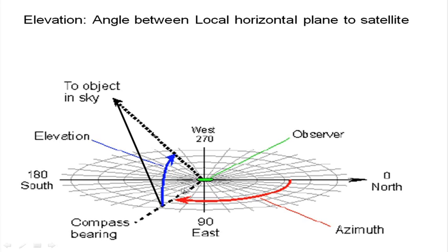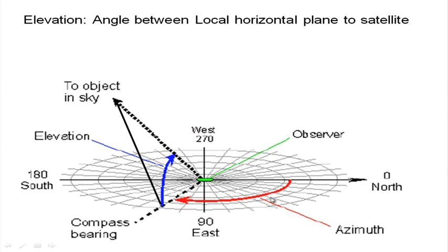The line joining the point which has cut, which is going towards the subsatellite point. So, this line to the line joining the observer to the satellite, this angle is elevation. That means you are looking from the horizontal plane, going up and looking towards the satellite, and also this angle has to be rotated from the north eastward.